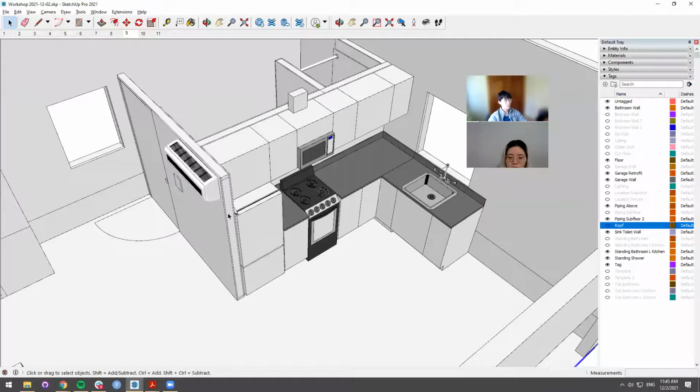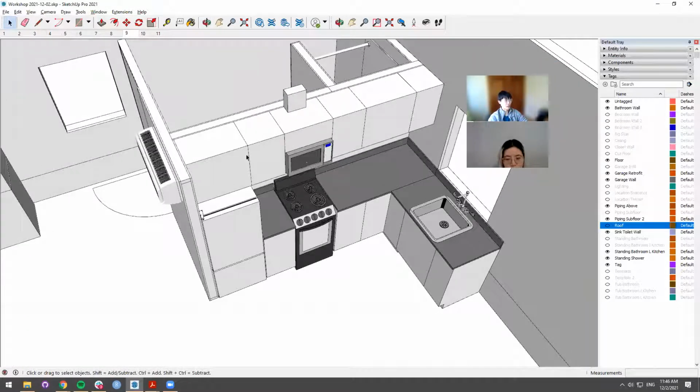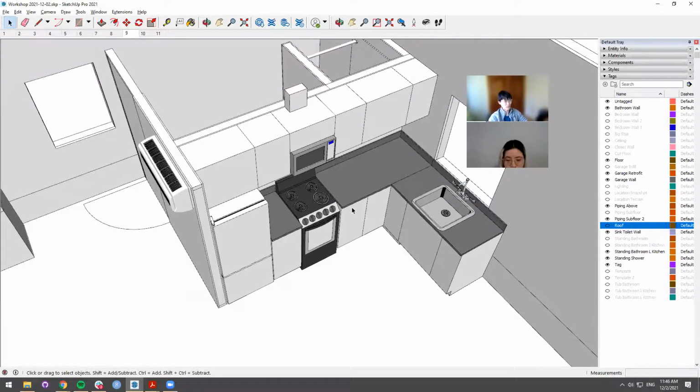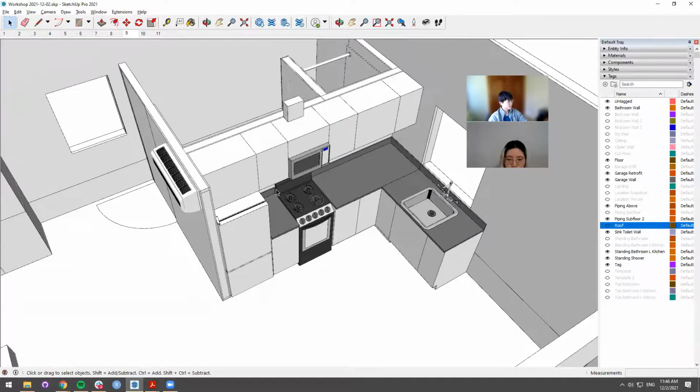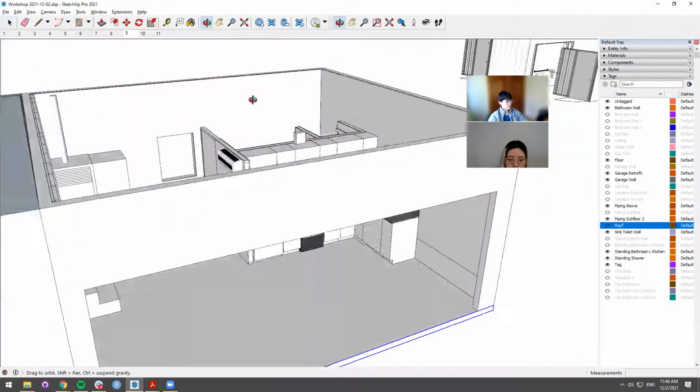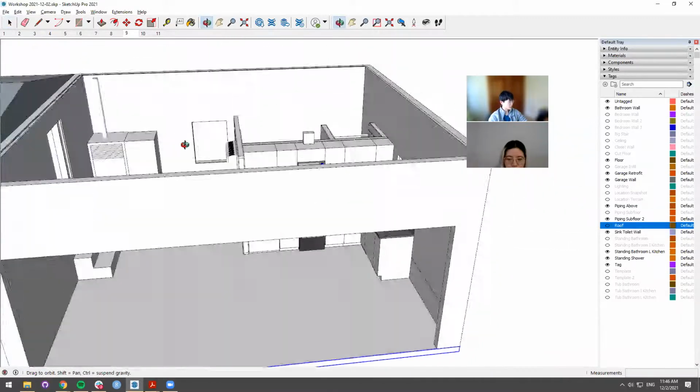This could be obviously, fridge comes in on its own. That doesn't need to be made modular. And big pieces, either the whole L or the L and 2 pieces could be brought in, roughly put together. You've got a flexible drain line for the sink that would make for an easy attachment under the cabinet to where the plumbing wall was. And then in this case, we propose a very, very narrow electric range, microwave hood, which will have an exhaust duct as well, because this definitely is a small counter for anybody who will spend a lot of time cooking. All right. So that's what its arrangement is in the space.